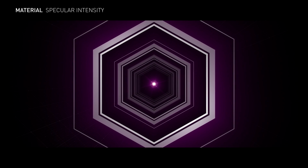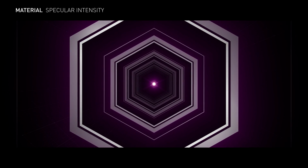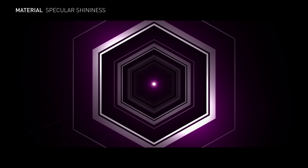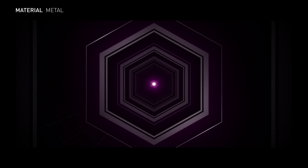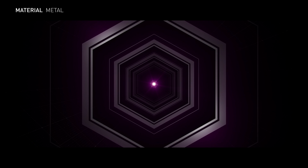Specular intensity is the directional reflectivity of the layer and how shiny the layer appears. Specular shininess is the size of the specular highlight and glossiness of the reflection. Glossiness can range from blurry to mirror-like. And metal is the contribution of the layer color to the color of the specular highlight. A value of 100% metal means that the highlight color is the color of the layer.